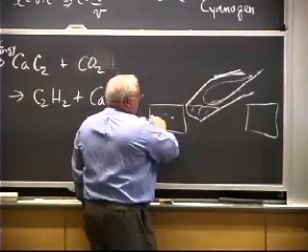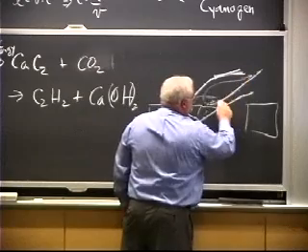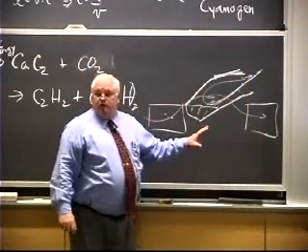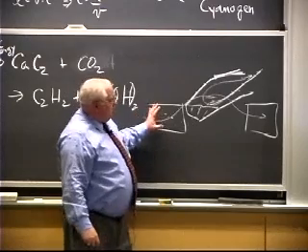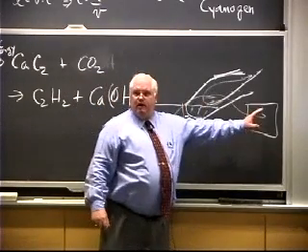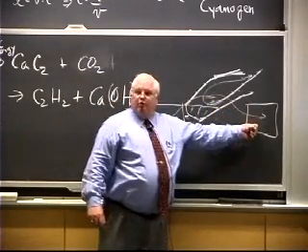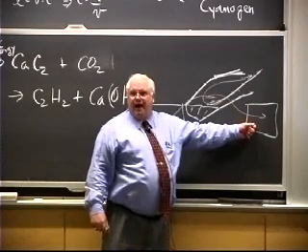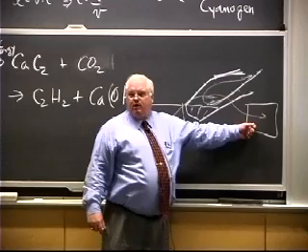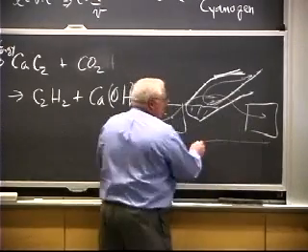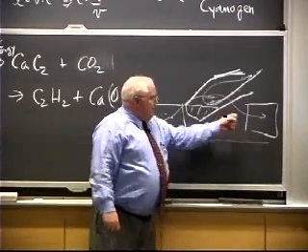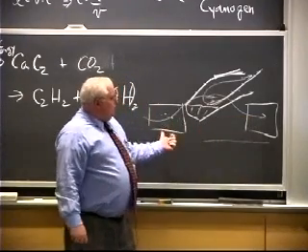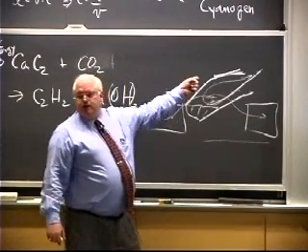And so you would have your hot gases come into the steel vessel. It's not the same steel vessel, and you have them exit on this side. What you would do in the open hearth is, for about 8 hours, flow the air in this way to refine the steel, and it would go past this football stadium-sized brickwork lattice, which had all been hot because before you used to flow it back through the other way. And so you're preheating all the brickwork with your exit gases, and then when you reverse the flow, you've got hot brickwork which preheats the gas coming in.